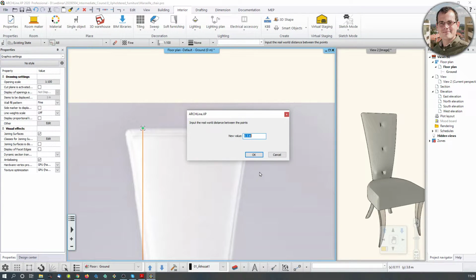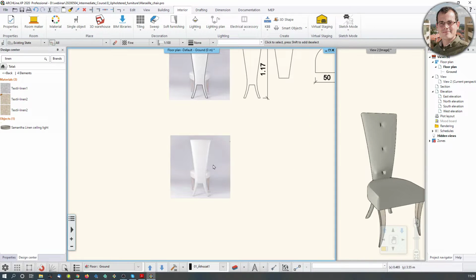My software is currently in meters, which I'm going to change in a second, but if you have a millimeter value, you can input that too. But make sure you're not hitting enter now, because then the image is going to be more than a kilometer high. So instead just say millimeters, hit OK. Okay, now the picture is calibrated.